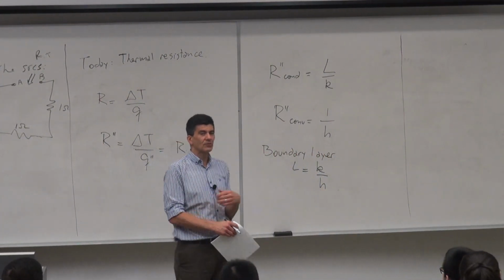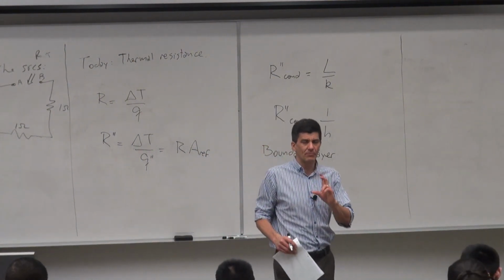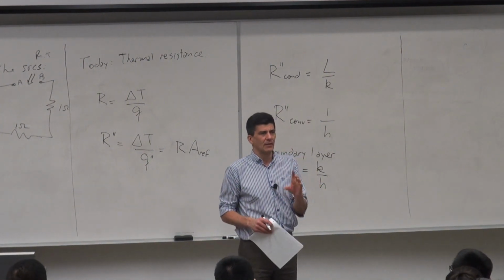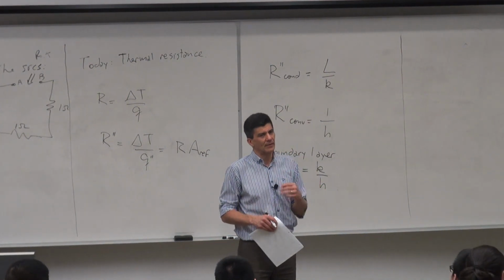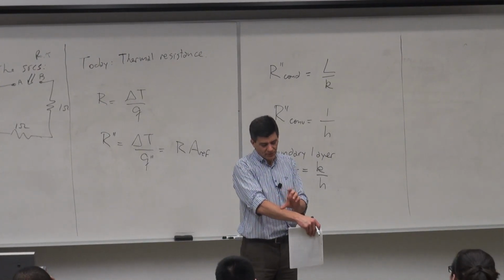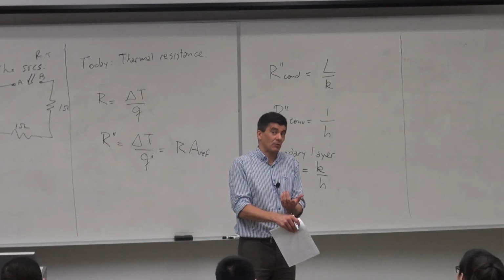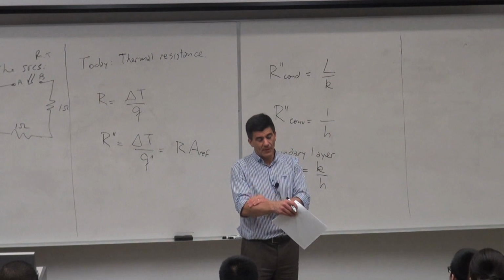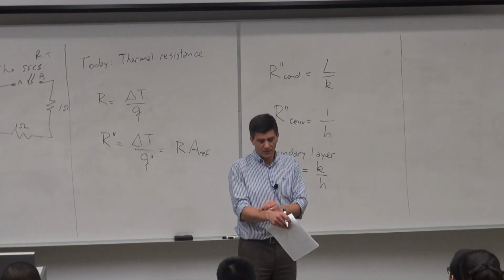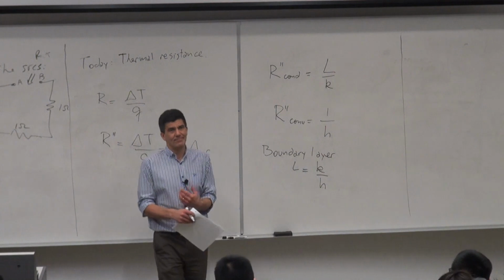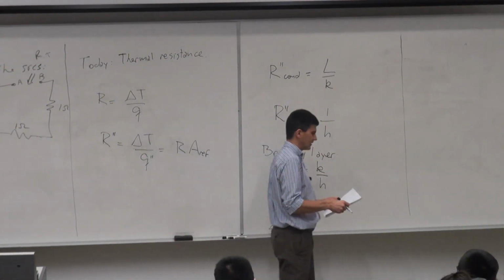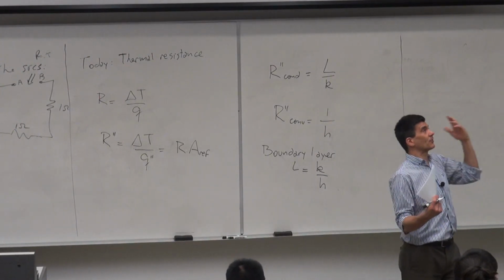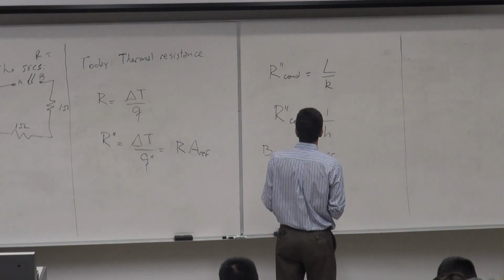And the reason I'm talking about boundary layers now and about this relationship between conduction and convection is because in reality, convection is nothing but understanding if you have a thick or a thin boundary layer, and that's what tells you how much heat you're going to lose. That's why if you have wind, the boundary layer gets thinner, therefore you lose more heat, right? And that's why a windy day is colder than a calm day. And that is also why swimming at 20 degrees is a lot colder than hanging out at 20 degrees air. All right, so